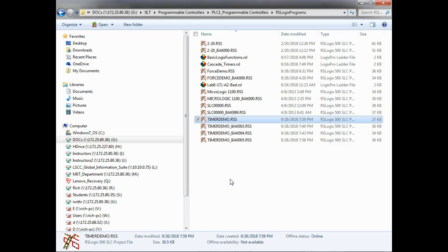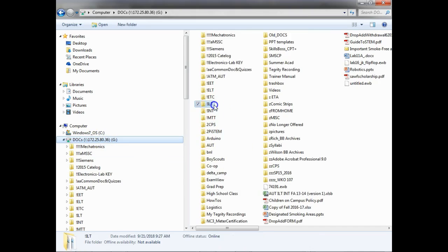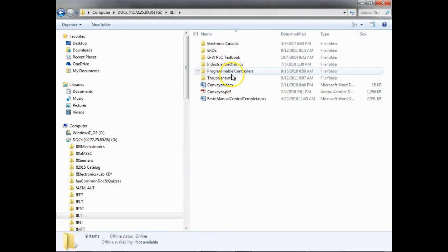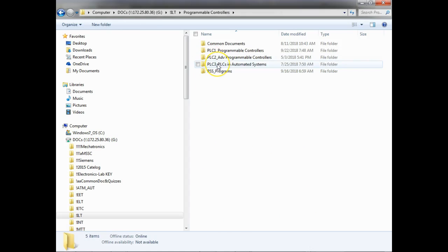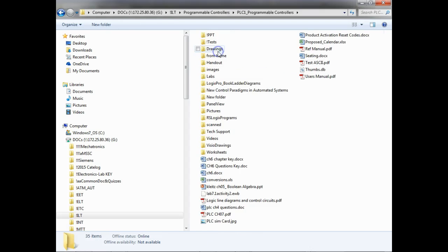The Allen-Bradley does not support up-down counters. Siemens does, so you get a count up and a count down input. Here you would have to do it mathematically, and we're not going to teach how to make an up-down counter with math. We can have coil counters, which Siemens Step 7 does, or we can have single input counters. So we use single input counters.